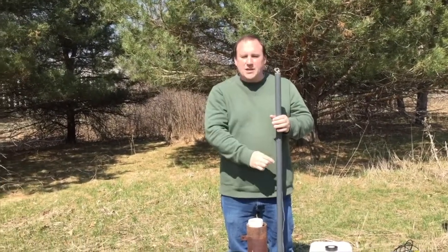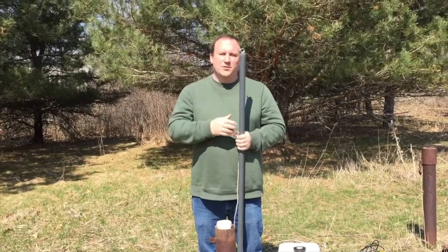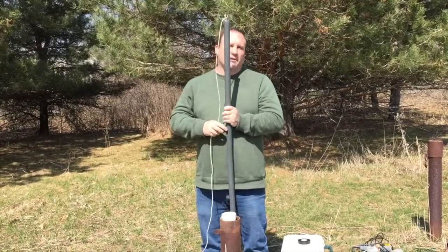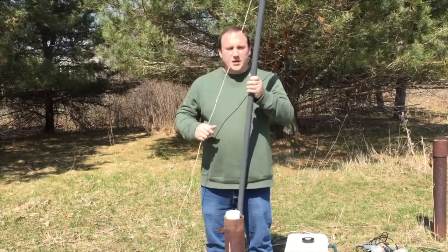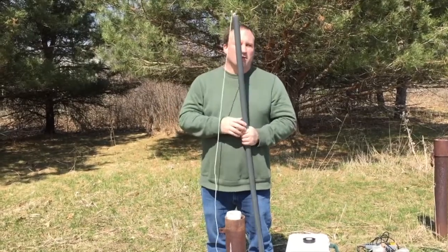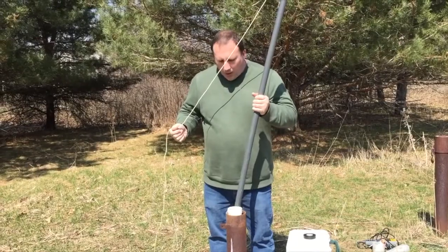pi r squared times h to calculate the volume. That volume is equivalent to an amount of water that we put into the well. And if you know the interior diameter of this well, then what we can do is calculate how much water was put in as an effective slug of water. So it's the same kind of idea. All right,